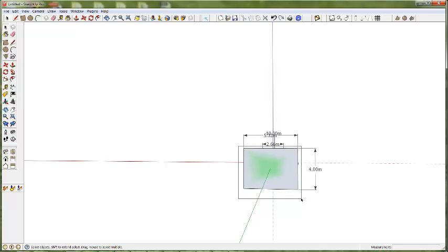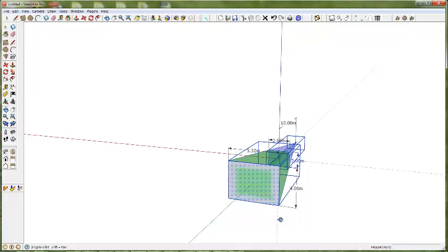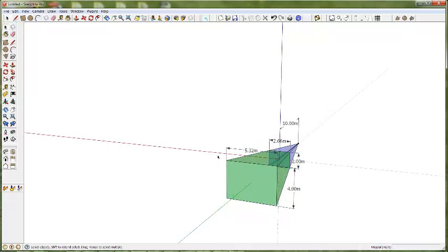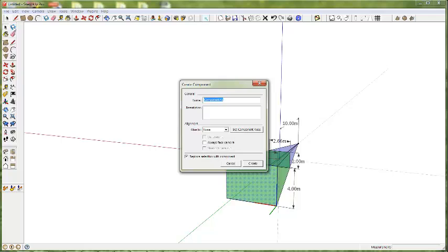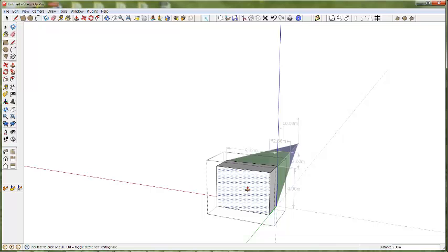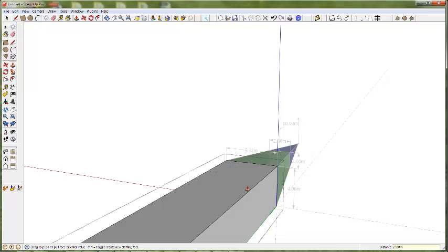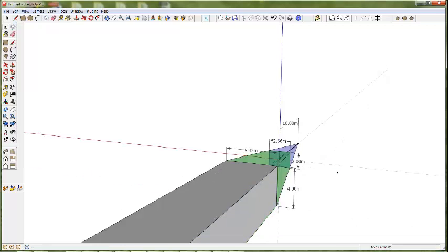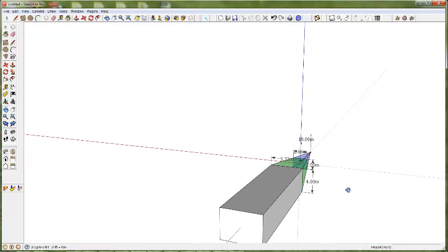So go from 4 meters to 8 meters for the field of view, which we'll do by extending out that face, doubling the displacement we already have, which is 20 meters, and double that out to 40 meters total, so extend it out another 20 meters. So I'm going to grab the face there, push pull, and extrude it another 20 meters, so now the total from the point of origin is 40 meters.